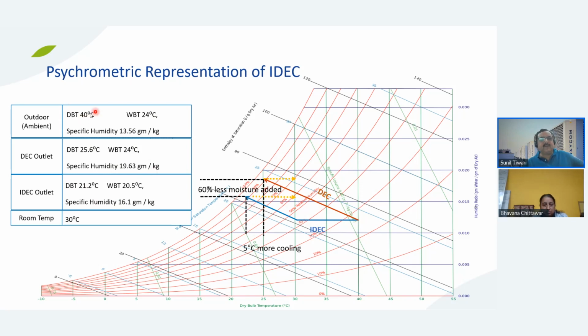Now, this cooling you got from direct evaporative cooling or indirect. So, we are talking of these tough conditions of India and average conditions. So, you can design a building, let us say, at around 30 degrees centigrade. So, the air comes in, picks up some heat of the room, typically the sensible heat. I am ignoring the latent part which it will absorb, because in any case this air is going to be thrown out, discarded. So, you travel this side and the room condition is stabilized somewhere here.